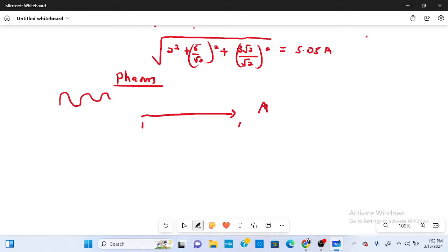So you can have a voltage and a current moving in the same direction. What we say is that they are in the same phase. The angle between them is 0 degrees. So your voltage and your current will be in the same phase. In a case where your voltage moves this way and your current comes down like this, you realize there will be an angle between them. This is what we call the phase difference or the phase angle.